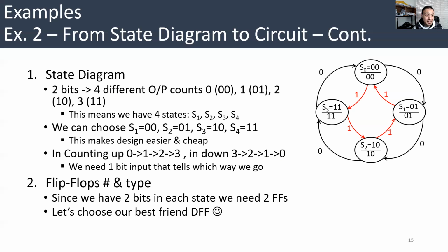But that doesn't mean it will be the one that leads to less hardware resources. You might use D flip-flops in a circuit, and the analysis and design were easy and simpler, but at the end we got a big circuit. With the same design using another flip-flop, the design process might be a little more complicated, but it might lead to less hardware resources, a more compact circuit at the end, a cheaper one, basically.